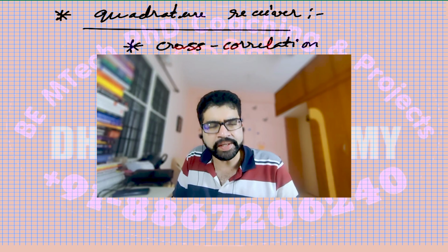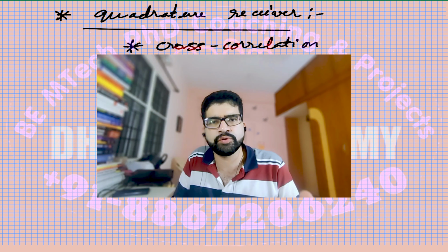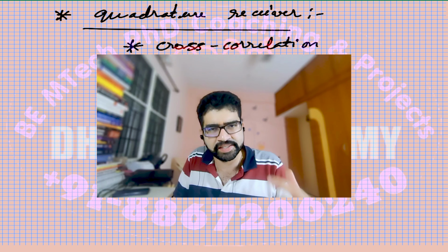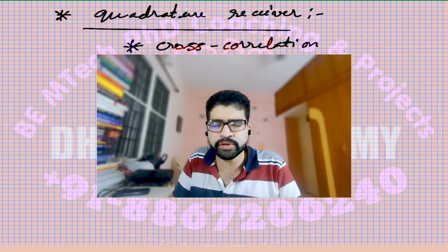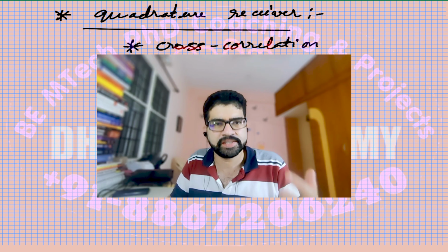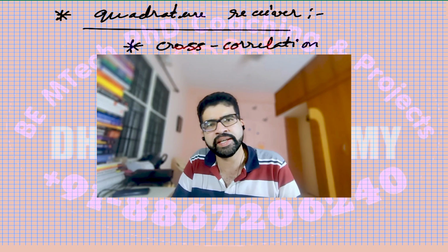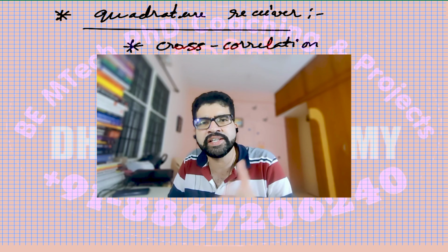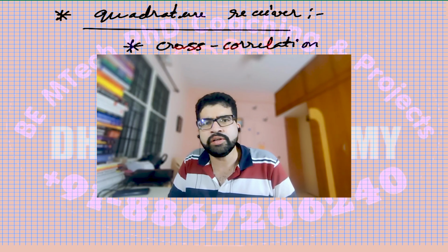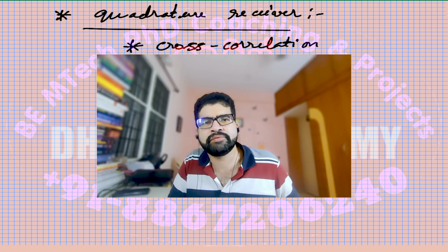Depending upon what signals you use for correlation, we have varieties of correlations possible. The first one is autocorrelation, where you correlate a signal with itself. Auto indicates with itself. Let's assume I have a copy of the signal, but it is shifted, like I have x of t and x of t minus t naught. Depending upon the t naught value, it can be left shifted or right shifted.